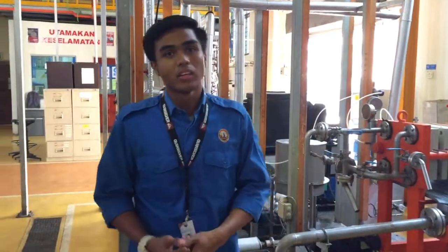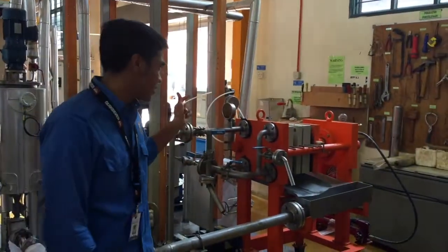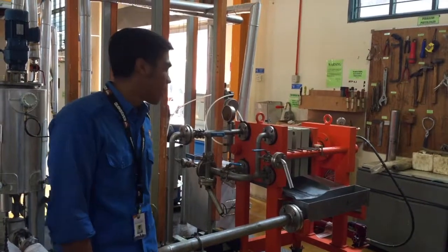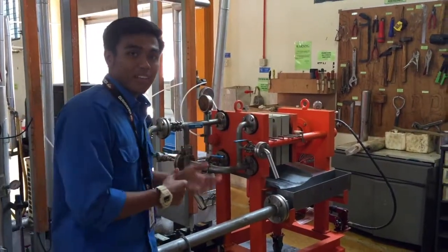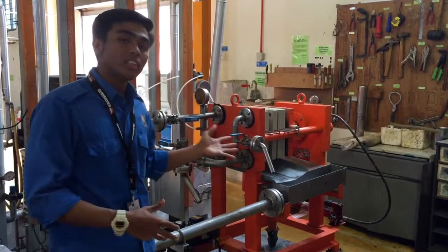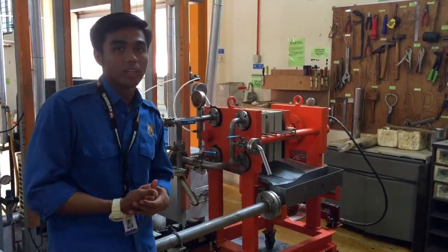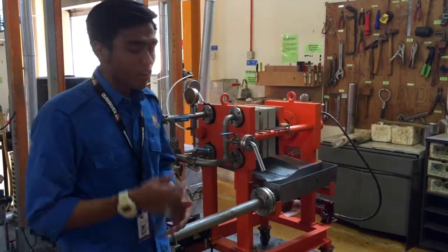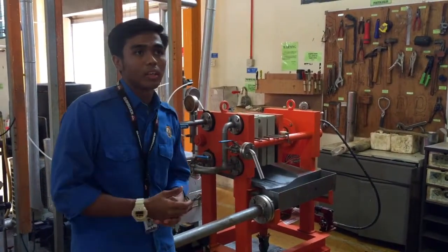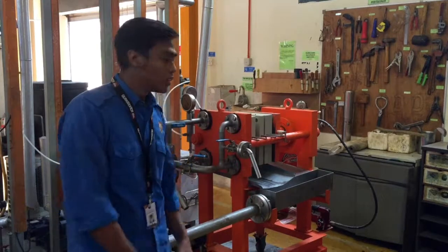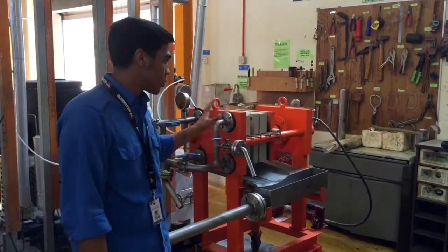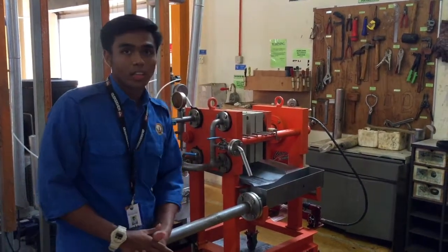So, going to the next process, which is after the crystallization process, we are going to proceed to the filtration process. Here, as we can see, is the machine for the filtration process, which is the plate and filter press machine. This machine will separate the products required for this experiment, which are the stearine and olein. Stearine is basically in the form of solid, and olein will be obtained in the form of liquid. So this machine will undergo the process to obtain those two products finally.